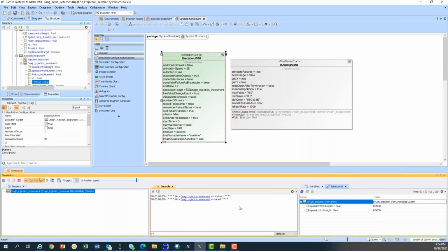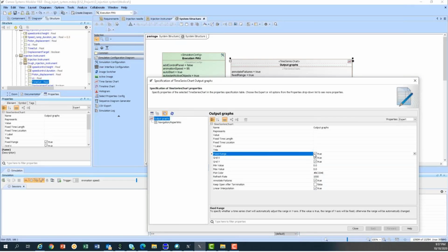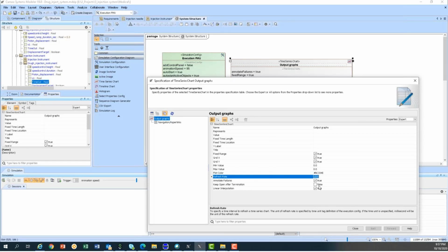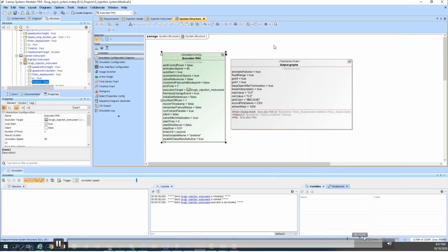Now, you can run your simulation. As you can see, the simulation is quite fast. You can change the causality, and also you can look at different ports. One interesting thing is that when you're running the simulation, during the simulation time, you can change or select different results. So it's not only at the beginning or at the end that you can apply some modification to your simulation. Even during the simulation, you can change some parameters, or you can select different types of inputs and outputs, and you can monitor them in your simulation.